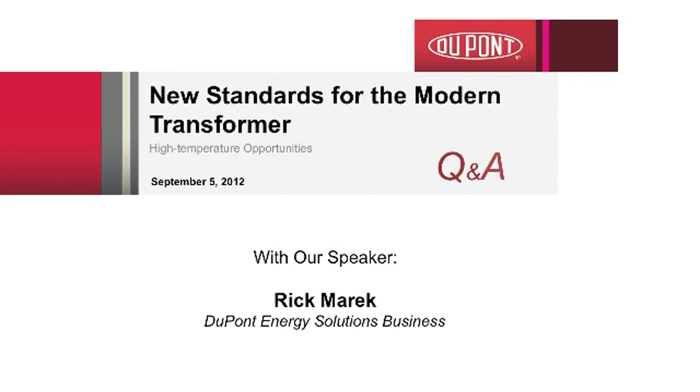I have a customer that wants to move up in class, currently using Kraft Mylar, and wondered if a Mylar Nomex will work, like using Nomex 410 in a laminate. Laminates are generally not recommended for use in liquid-filled transformers.